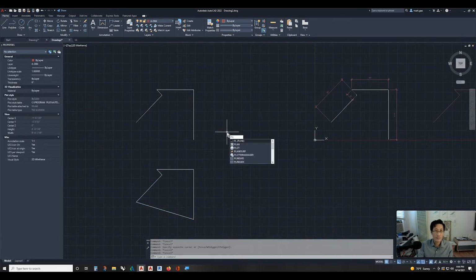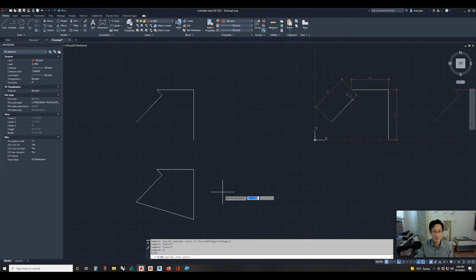we do the same thing. What you do is run through this very quickly. Angle 45, 10, enter. Angle 135, enter. We'll go 2. We'll go 10 inches the other way again. And now back down 13 inches.